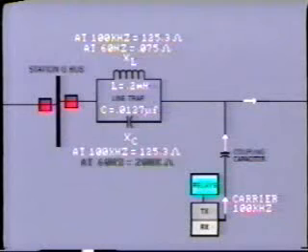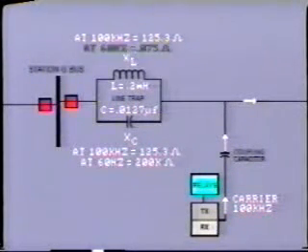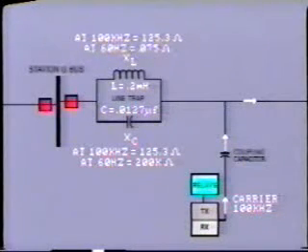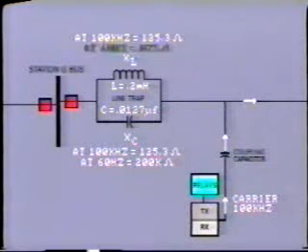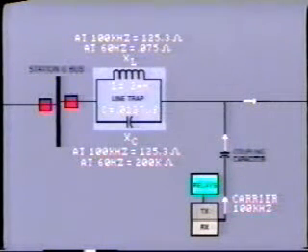But what is the effect of this capacitor at power system frequency? Well, at 60 hertz, the capacitive reactance will be equal to about 200,000 ohms. So we see that virtually all of the 60 hertz current will flow through the inductor, which has only 0.075 ohms. And what is the impedance of this combined resonant circuit at 100 kilohertz, the carrier frequency?